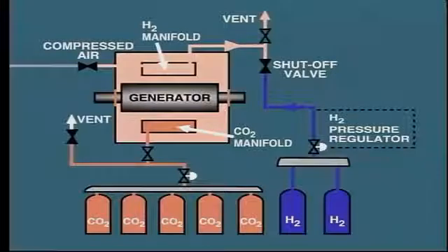During this process, the gas inside the generator casing is monitored, and when this indicates close to 100% CO2, air is admitted via the upper manifold to clear out the CO2. Now remember, carbon dioxide presents a suffocation hazard when encountered in a confined space. The total time required for purging may take several hours. When the generator is to be readied for service, then the reverse action takes place.